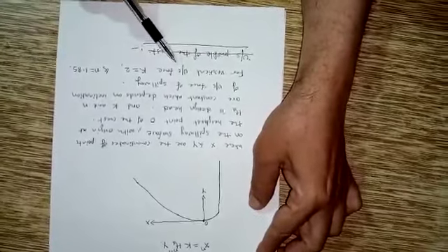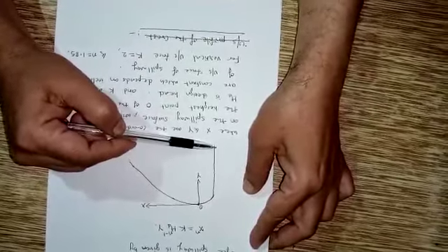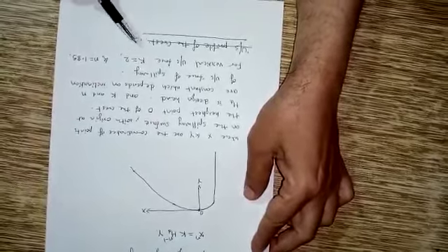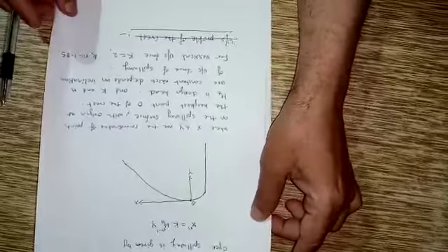Thus, for a vertical upstream face of the spillway, the constants K and n are given as K = 2 and n = 1.85.